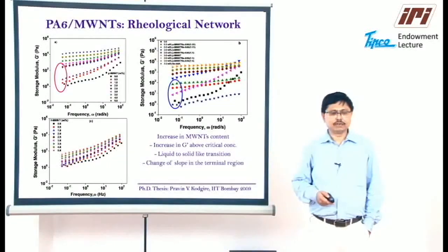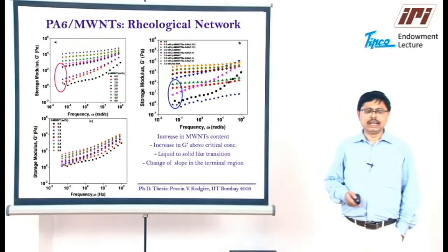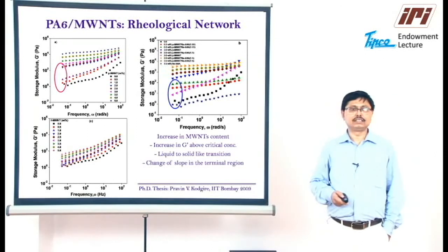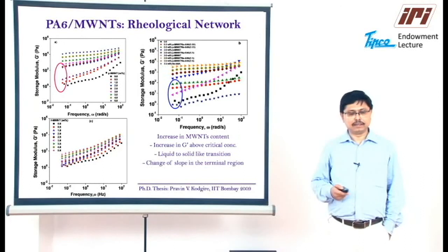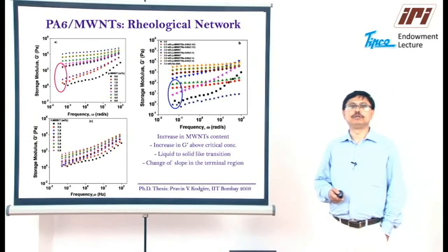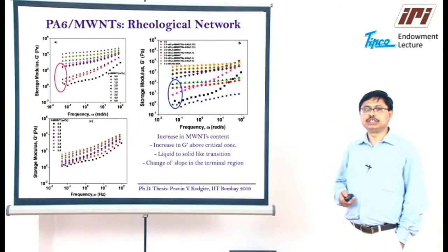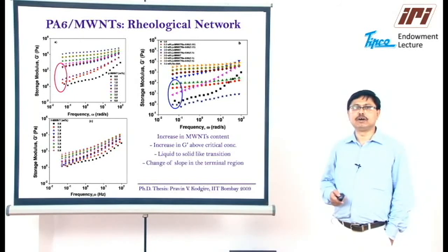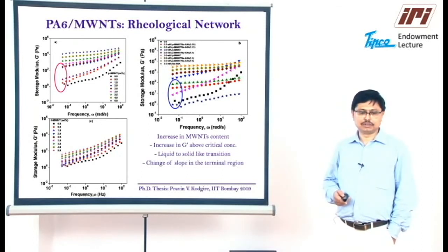The rheological network-like structure formation in these composites was also characterized through dynamic oscillatory measurements in the melt rheological experiments, for the purified multi-wall nanotube composites, the functionalized multi-wall carbon nanotube based composites, and the composites incorporating NaHA modified multi-wall carbon nanotubes.